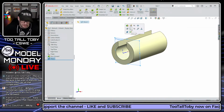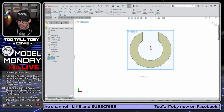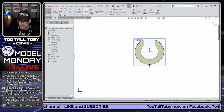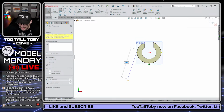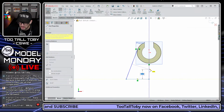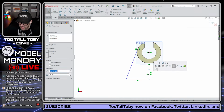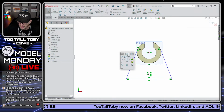So select a plane or a planar face, begin to sketch, orient our view. And for this leg here, we could maybe start out by doing a convert entities for that outer section. We could create this leg coming down like so and over. And then we could come up here a little bit, hit escape, take that line, make it for construction, take all these lines, choose to mirror across that center.